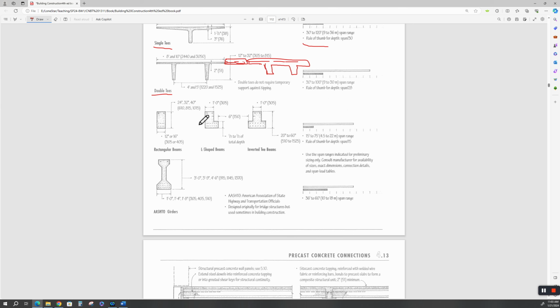The safest thing, in my opinion, is pre-stressing, because it's manufactured in a plant and then it's trucked out to your site. You can control what's going on in the plant, and you can do some preliminary testing, ultrasonic testing on those panels and beams before they get out, and you can catch the problems before it gets erected.